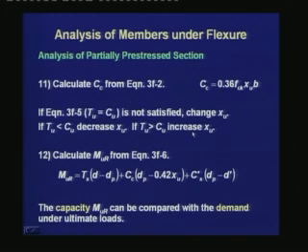Thus, if the tension is less compared to the compression, then we need to reduce Xu such that the amount of compression going to the concrete is less and the stress coming to the steel is more. On the other hand, if the tension comes out to be larger than Cu, then we need to increase Xu, thus having more compression in the concrete and lesser tension in the steel. Like that, we iterate till the first equilibrium equation is satisfied within tolerable limits.